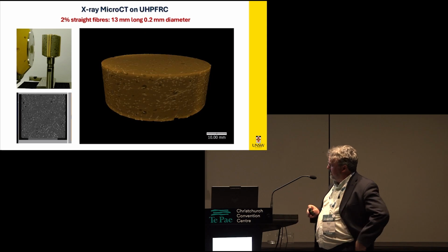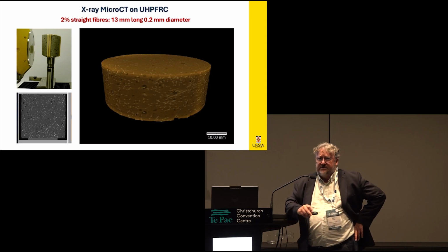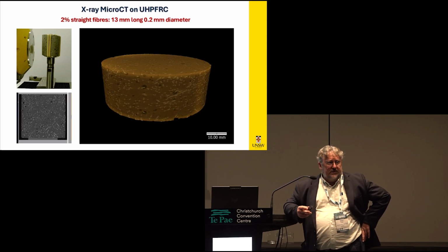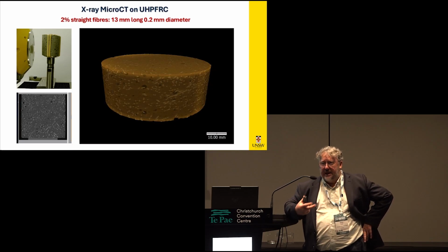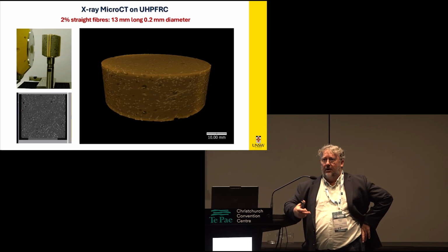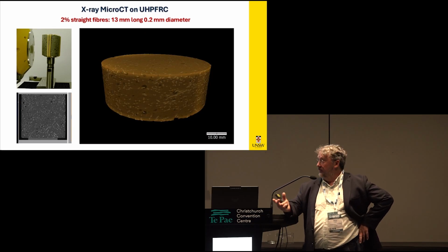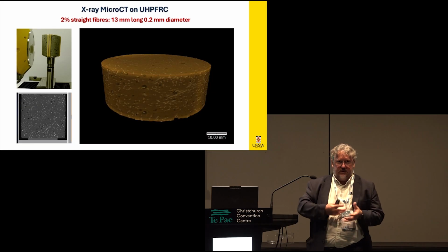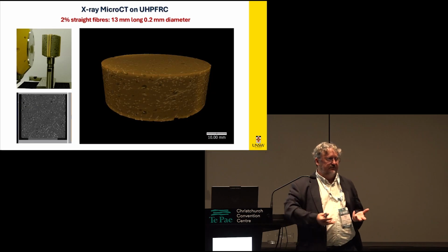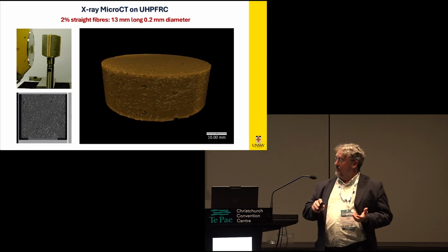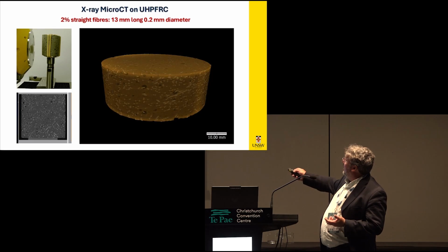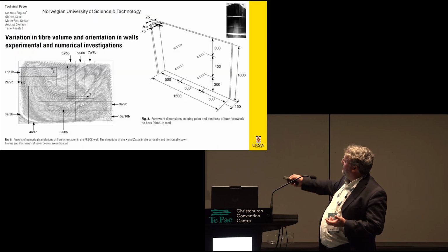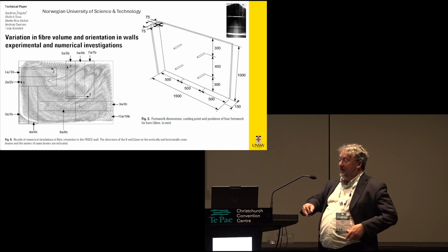I just want to show this, just to emphasise that when we're dealing with these materials, how we place them is really important, right? Whether it's fibre-reinforced concrete, this is a fibre-reinforced concrete example, or ultra-high-performance concrete, we make certain assumptions about distributions of fibres. And if we do things like, for example, put in form ties across the forms, we can induce weak spots, which can greatly impact the design.